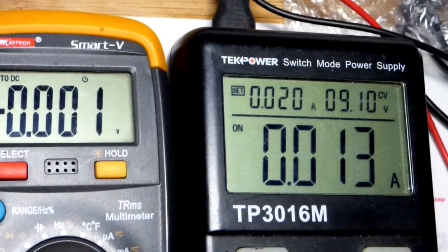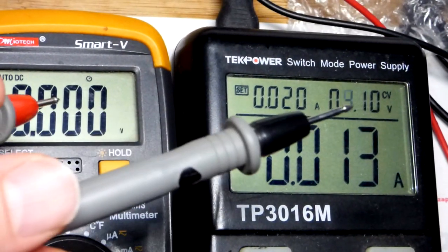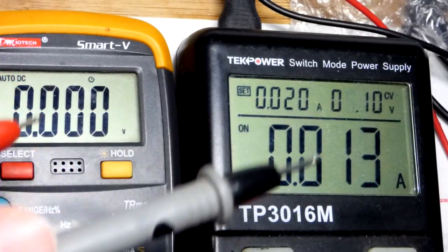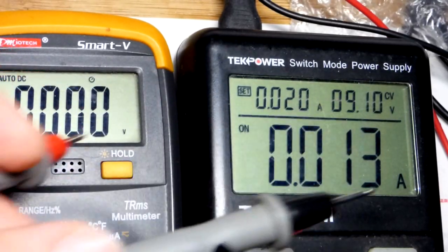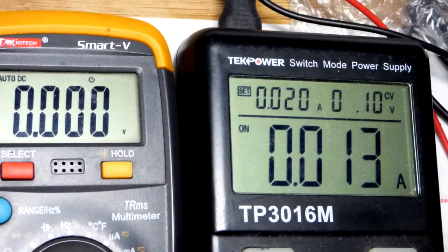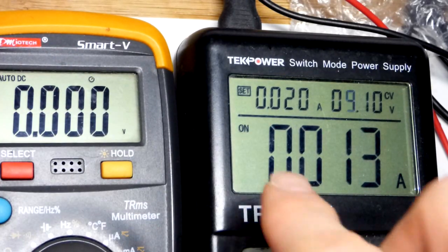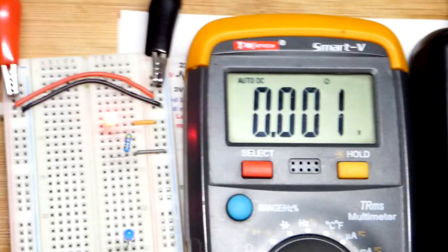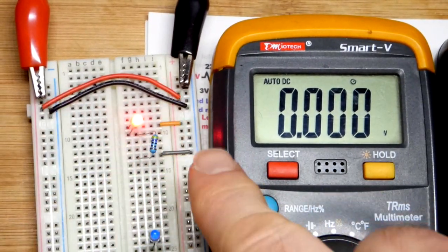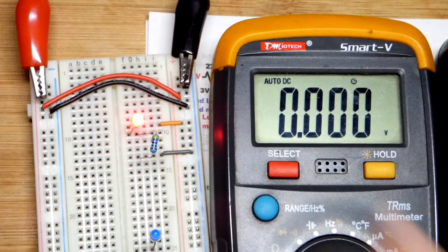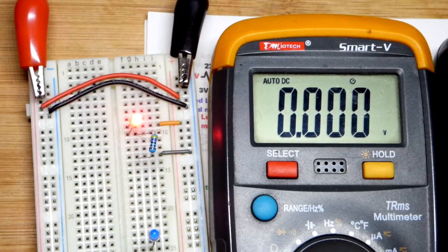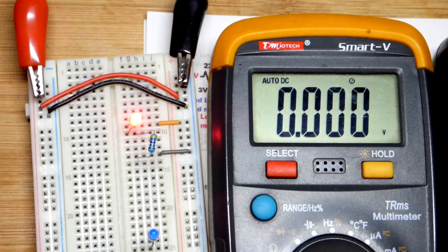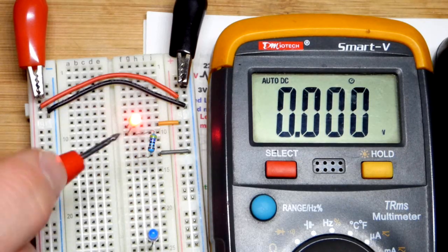That's why when you do Ohm's law, you take the supply voltage, subtract the diode drop, and then the rest of the voltage across the resistor is what will ultimately set the current through the entire circuit. The power supply, the resistor, the LED, all the wires, and so on, everything else has a little bit of resistance compared to the resistor, and so they're going to lower the current a little bit more. They're going to build up a little bit of voltage across them. We could look at that right now. So we have the resistor right here. This would be the more positive side.